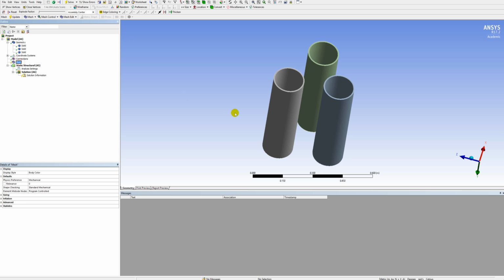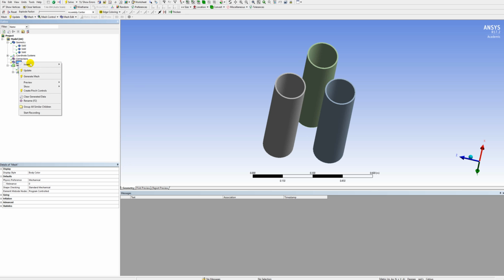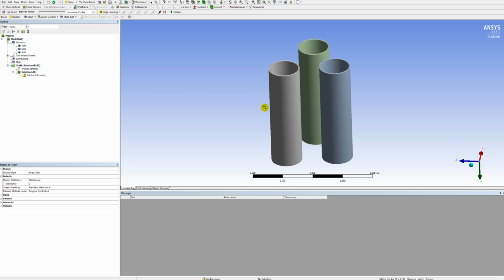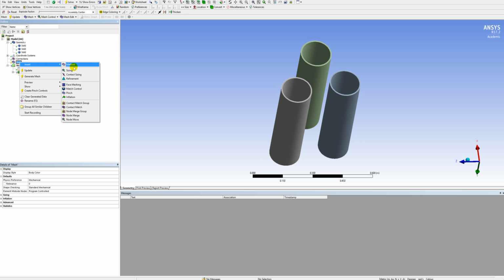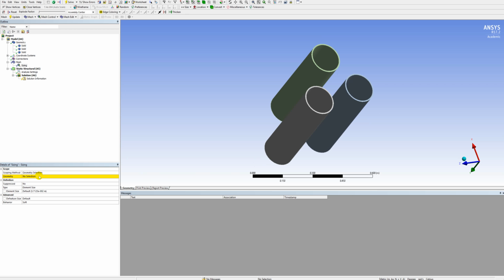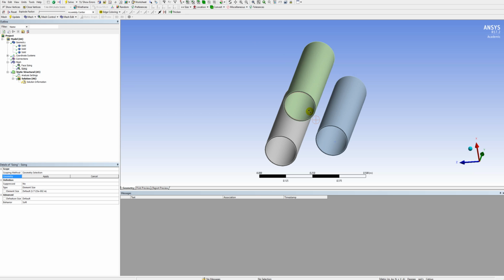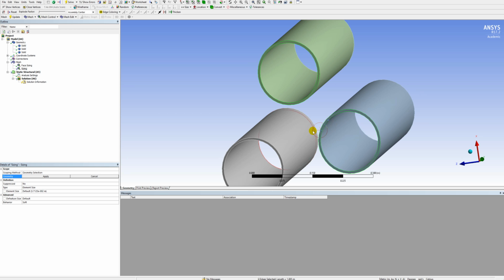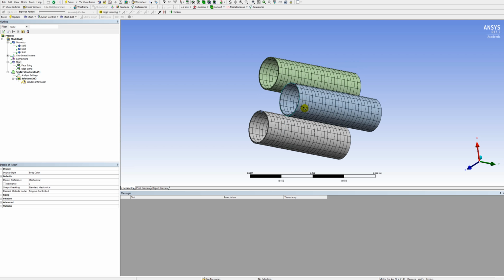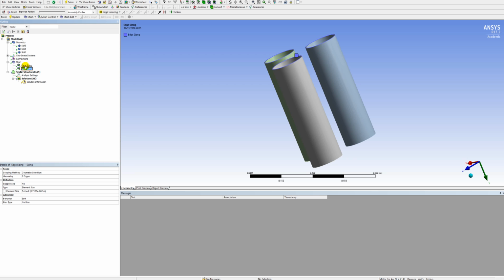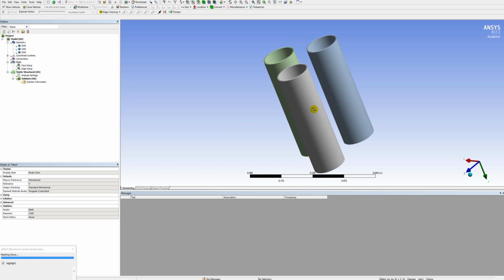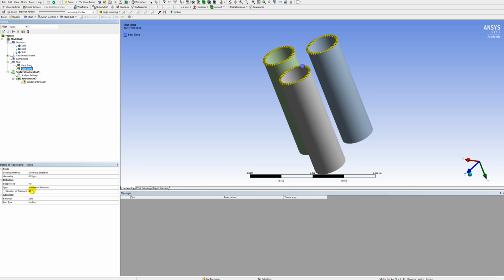Alright, next up is to mesh the bodies. There's not a whole lot involved in meshing these bodies. You guys can just go ahead and generate the mesh, but my version of ANSYS has some problem size limits, so I'll need to insert some sizings. So I'm going to go ahead and do those. You don't need to follow along, but you can watch if you want to. Fun fact, when you're doing edge sizing like that, you always want to specify number of divisions.